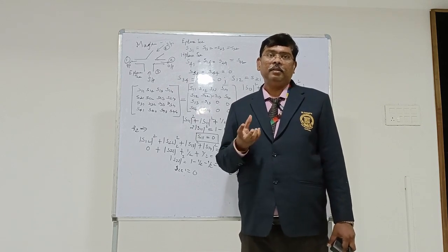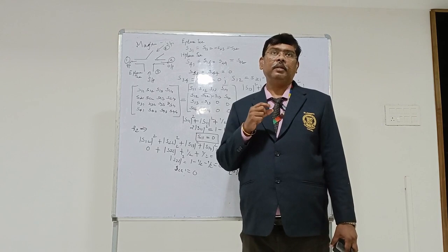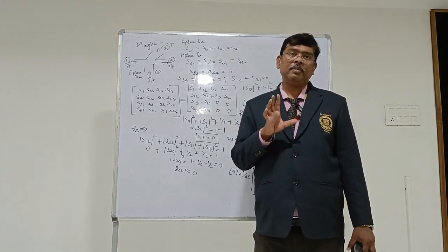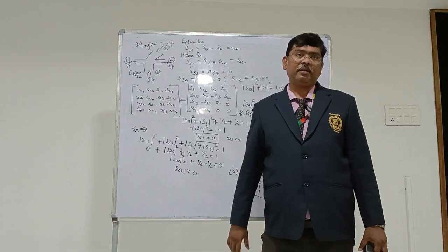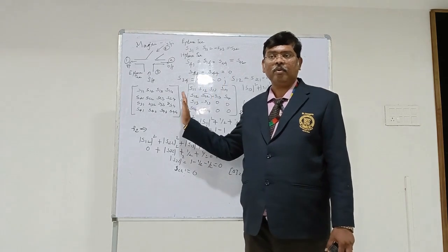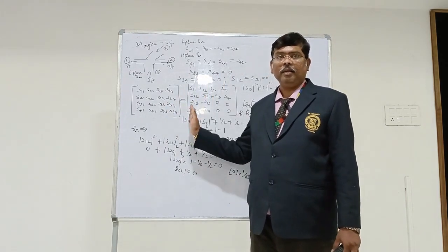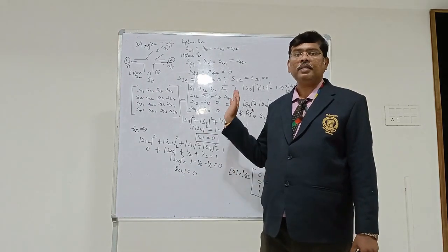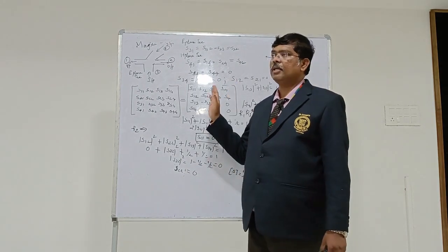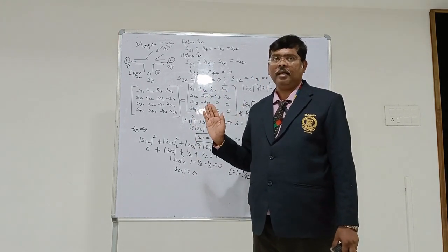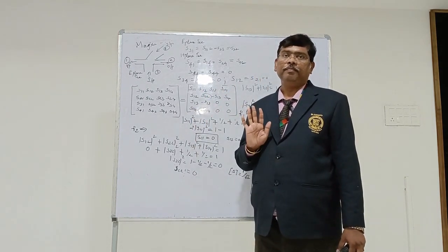These devices have some ferrite pieces, a ferrite rod, which produces the non-reciprocal property, whose forward characteristics are not equal to the reverse characteristics. These are the reciprocal devices. In the previous session we discussed the E plane, the H plane, the magic T; all these are reciprocal devices. So the condition applies, called the symmetry property, which means Sij is equal to Sji when i is not equal to j.